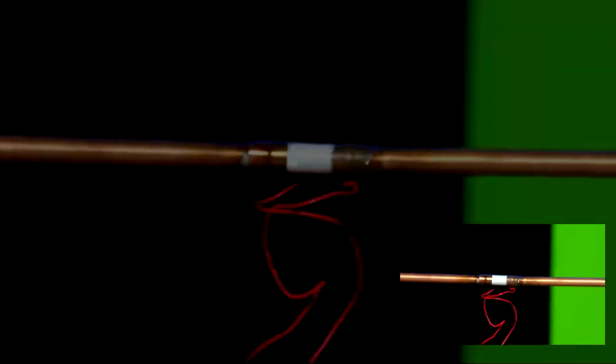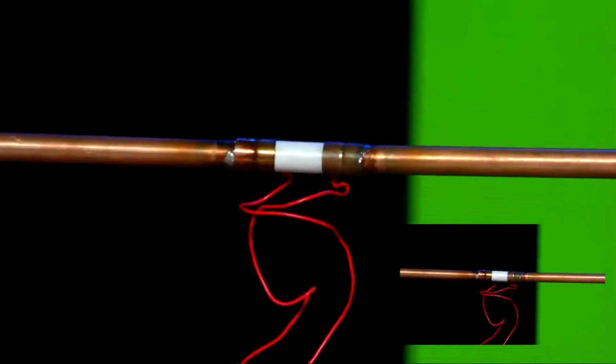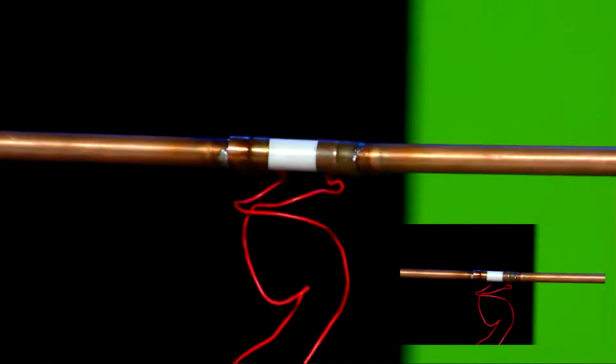RFID, near field RF technologies are usually just brute force. You don't have fancy antenna configurations and weird patterns and grills. It's just more metal basically, and bigger. So in this case, 1 square meter of copper tubing from Bunnings and a lot of burnt fingers and solder mess later, we have this.